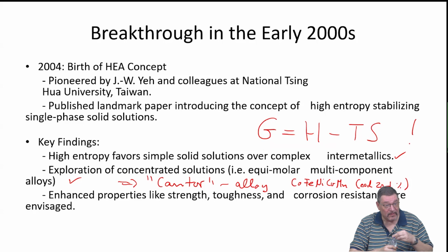You're right, no. There are temperature windows, lower temperature below 800 degrees centigrade, where a second phase precipitates out. And that shows you the concept is nice, having a high configurational entropy, but it works only if the temperature is also high, right? Because the product term, temperature times entropy, is really what you have to compare with the enthalpic term.